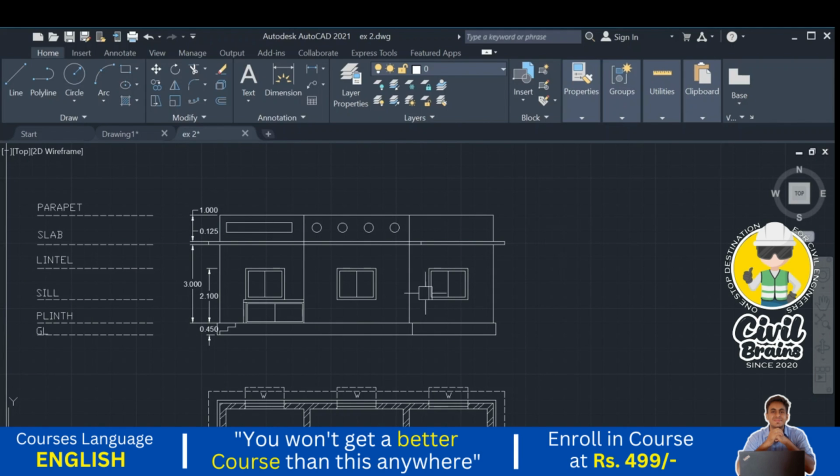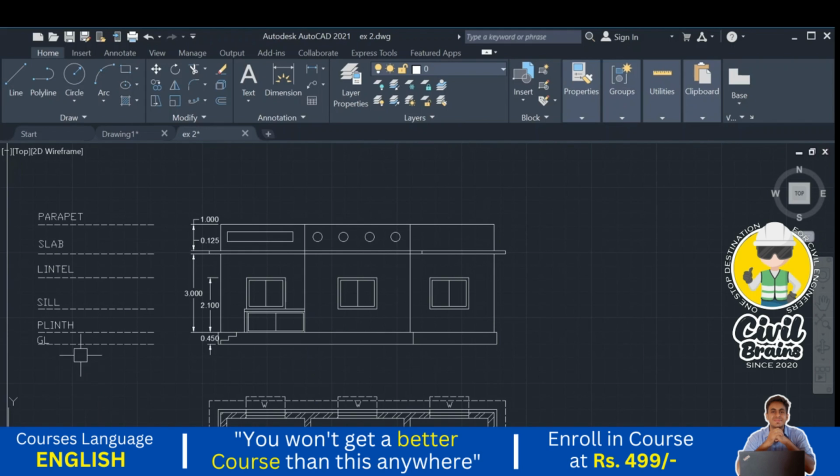In the elevation you can do whatever designs. In the elevation, the important thing is these levels. These levels are the very important part. If you provide these levels at proper levels, then the contractors, the clients, architects, everyone who is working on this side can easily identify these levels. So in the elevation, the design and the levels are the important part.